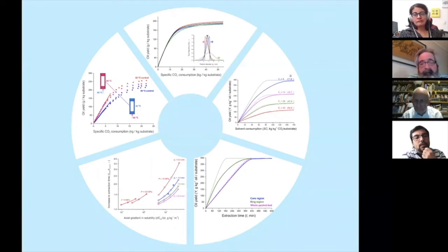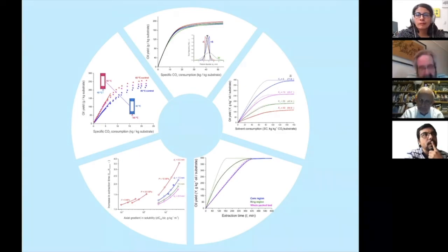So you have to describe your packed bed very well, and also the extraction conditions, obviously. In one of our cases, we had to fit, for example, the saturation condition because of some problems in our extract; the extract contained oil, and the solubility was higher than predicted by our correlation.